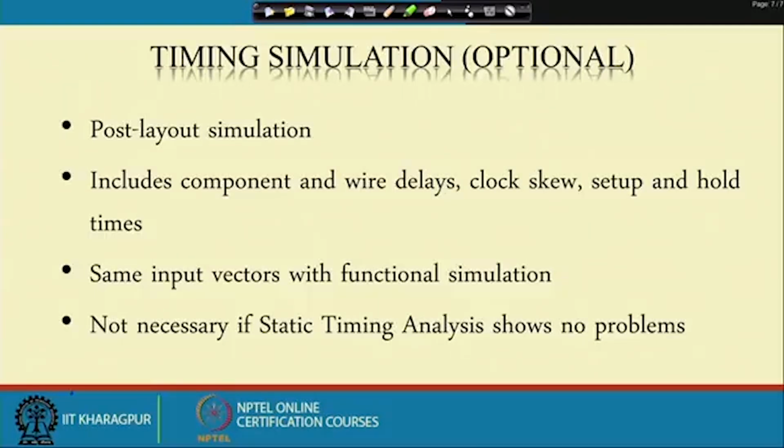In timing simulation, you put the test vector to the adder and check whether you are getting 2, but also after how much time of applying the input you are getting the output. That is also included in the timing simulation. That is the basic difference between functional simulation and timing simulation.